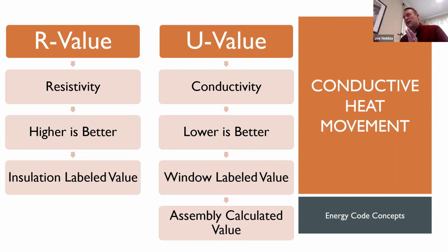And this is when you get a little bit into effective R value or effective conductivity, excuse me, because the U value for an assembly, a wall assembly, for example, takes into account everything like studs and stud spacing and framing factor and sheathing and things like that. And it builds up a U value for that assembly. So if somebody says, well, my wall has an effective R value of this because it's got a framing factor that's different than the code, they really need to be using U value in that case for compliance.